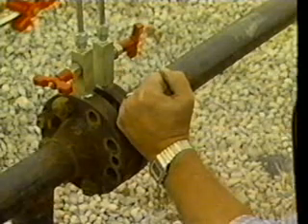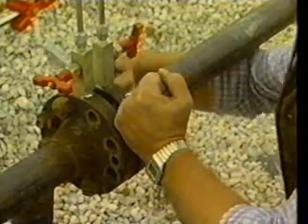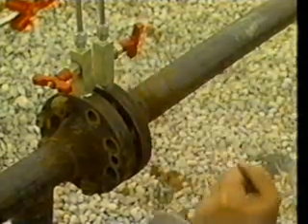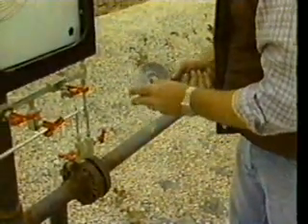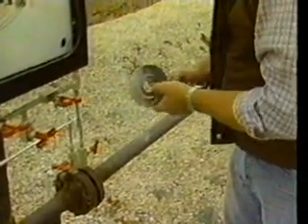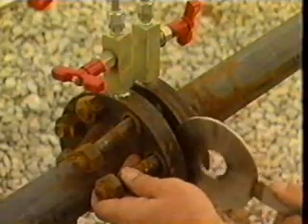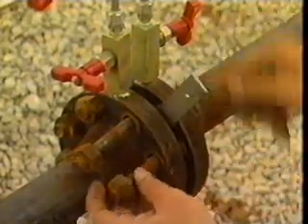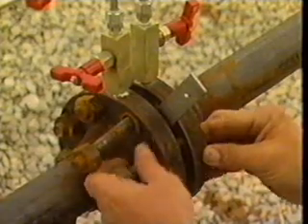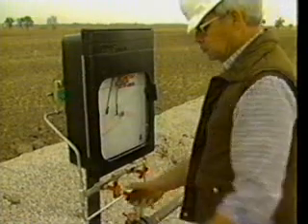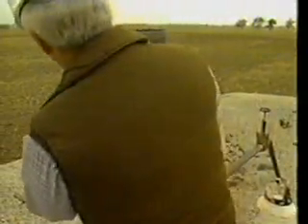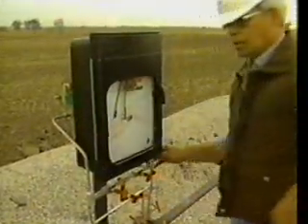Making sure that the orifice meter has been isolated and depressurized, then pull and inspect the orifice plate. With a senior orifice fitting, the isolation would not be necessary, but instructions for pulling the orifice plate should carefully be followed. After replacing the orifice plate, put the meter station back in service. Check for leaks and note the flow rate and recorder operation.